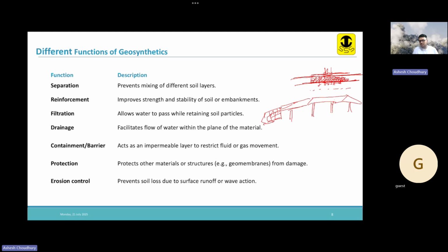So for this purpose, to construct this approach area, instead of making piers, we construct a reinforced earth wall. We reinforce the soil so that we can construct an approach road over it. Or else say we want to construct a steep embankment. Generally with the available soil, you are able to construct an embankment like this.